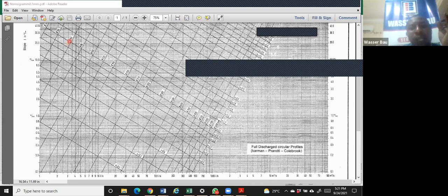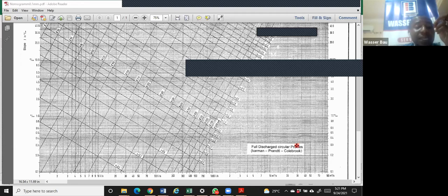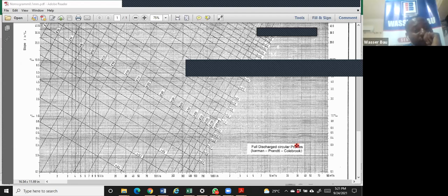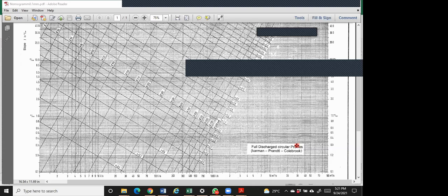That's why in engineering, you also have to look at the local conditions and look at the standard. This chart was calibrated in Germany. In Germany, they have DN65, I guess. But we that are using British standard, until recently that they've harmonized, I don't think we have 65 mm. Then what we have here is 50 and 75. But wait a minute, I think we have a 2.5 inches pipe in the market.